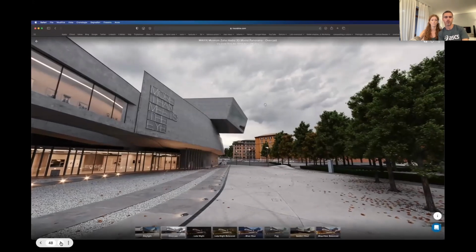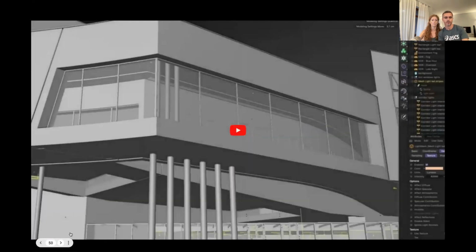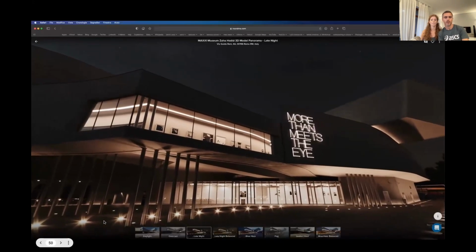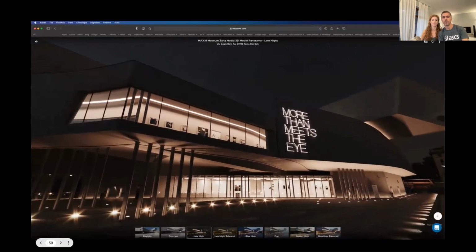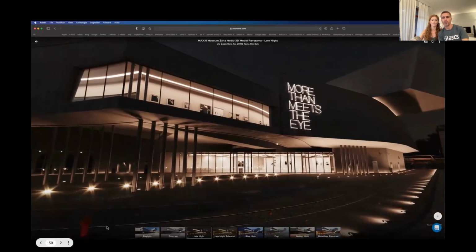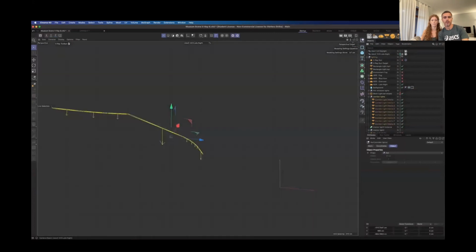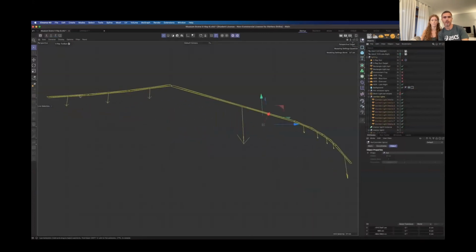Now let's talk about mesh light. On V-Ray 5, there was no mesh light option to get light strips, neon, and other complex light sources. So you always needed some workaround to do that. In the old scene, for example, I created many individual area lights over here to create this shape, and I assigned a custom intensity for each one. Of course, this is not ideal.